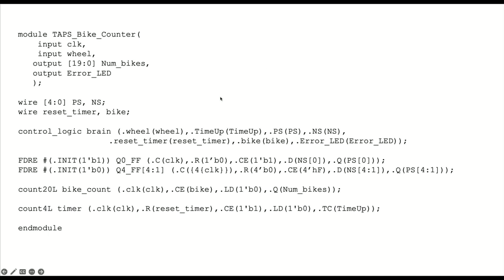And if we were to take everything here and jumble the order, you'd get the same circuit. The only thing you need to worry about in terms of order is that you declare the wires before you use them. But otherwise, we can permute the lines in your modules and it won't change anything.